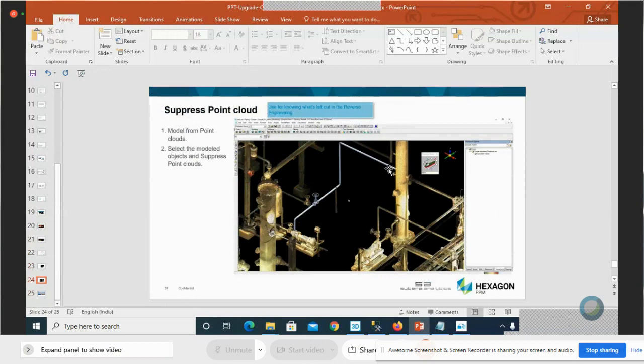And one more good thing is that this cloud data, whichever we are integrating in Smart 3D, will participate in IFC checking, interface checking. This means you will clearly understand wherever the clashes are. So these are the additional features in 2019.